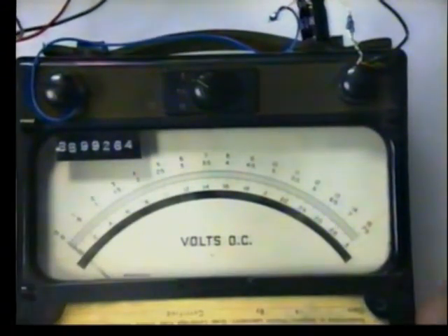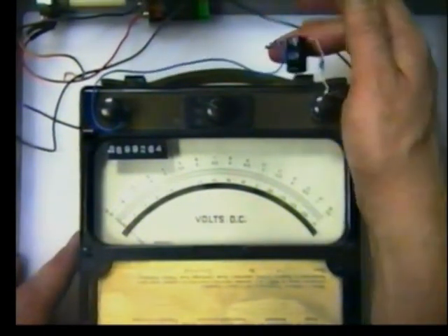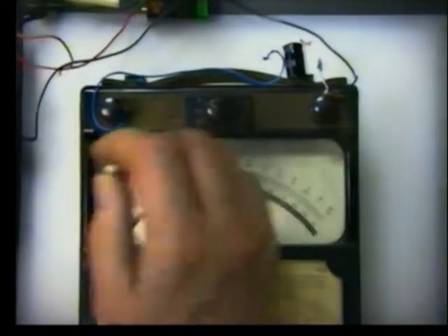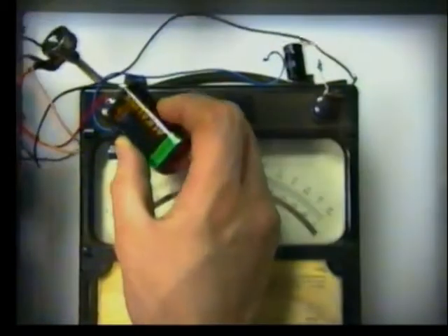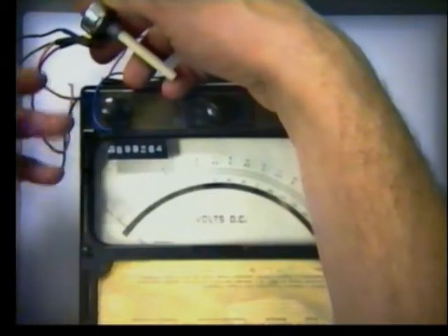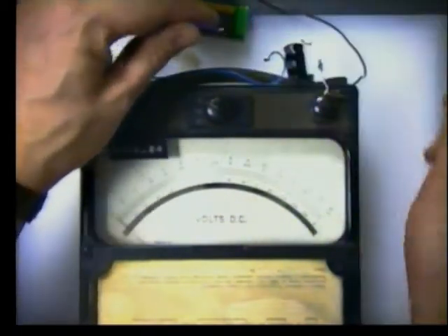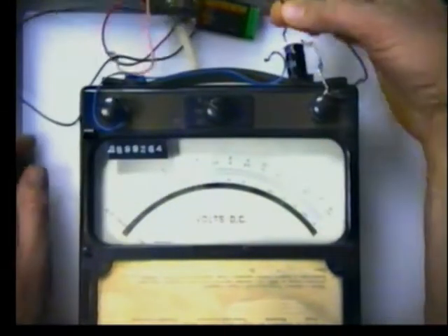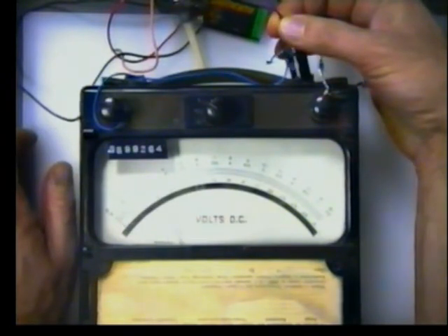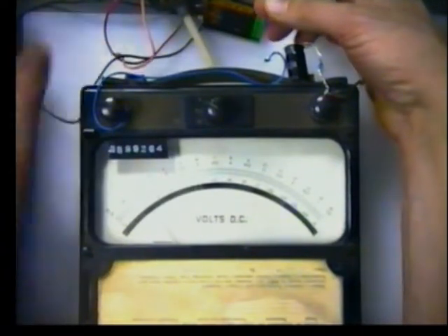But it's an old moving coil meter like you get out of old science fiction films. Here we have a capacitor, a charging capacitor, and this is a simulation of an ADC. What I have here is a simple little 9-volt battery and a simple little twiddle pot, a potentiometer like a volume control on a hi-fi, and all this does is vary the voltage. And what I wanted to show you was an ADC, a dual slope ADC. So when I attach the voltage, it charges up and then it discharges.